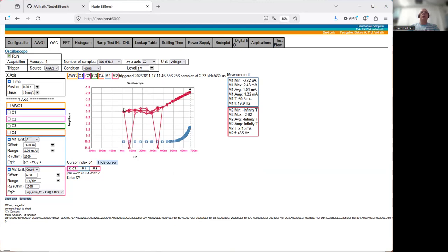Down here, this is measurement errors. This is basically where I have the limit of my analog to digital converter, so that the voltage drop along the resistance is too small, so that my calculation of my current is minimum and limited by the least significant bit. This is all I want to show you for measurement of a diode. Thank you for your attention.